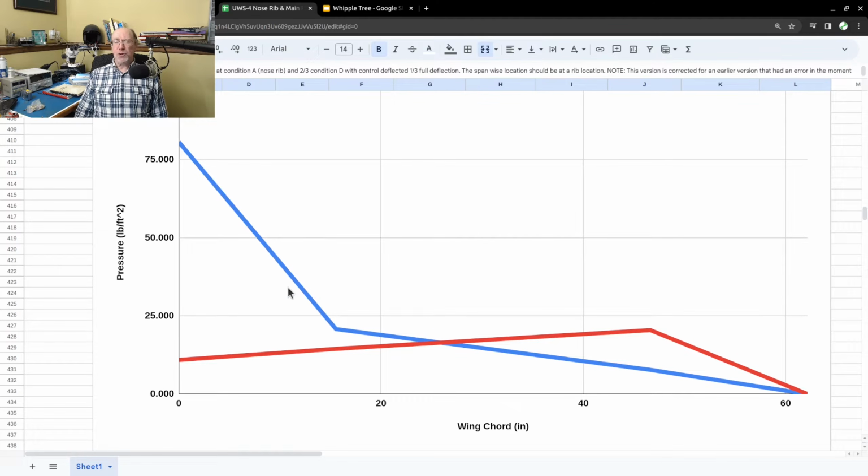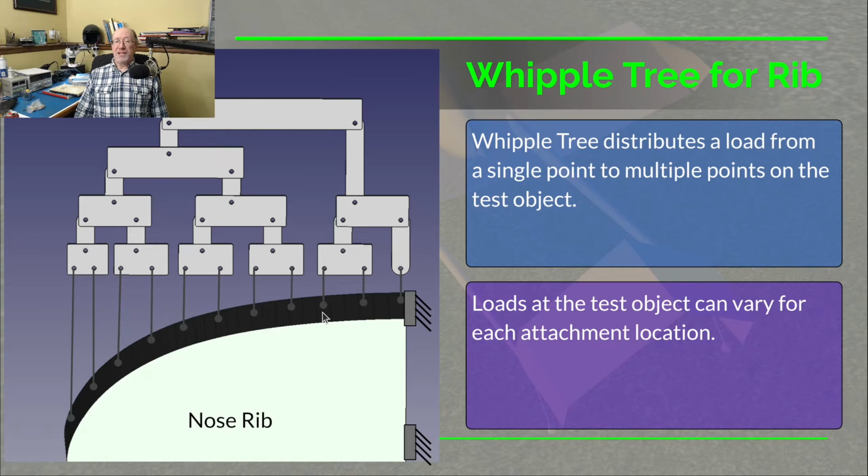So that means it's going to trend closer to the triangular centroid. So it should be closer to 6.5 inches than it is to 9.5 inches. Now we said it was 7 inches in our final calculation, so we're at least in the correct ballpark. So we did a little sanity check. The numbers aren't completely out of whack.